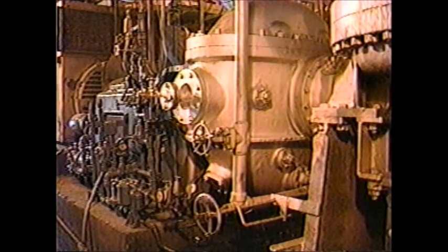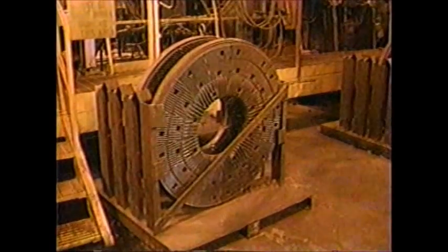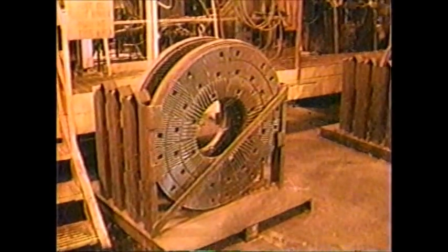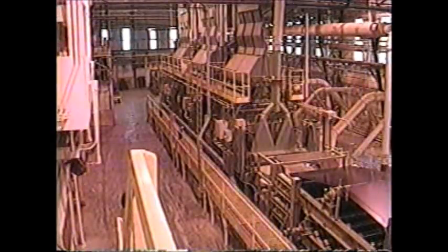The cooked chips then pass through a refiner, which employs a stationary and a rotating pattern disc operating at close tolerances to convert the chips to fine wood fiber. These are refiner discs. After leaving the refiner, a water glue emulsion is added and the fiber glue mixture is dried in a blow tube dryer. The dried mix is stored in bins until needed in mat forming.